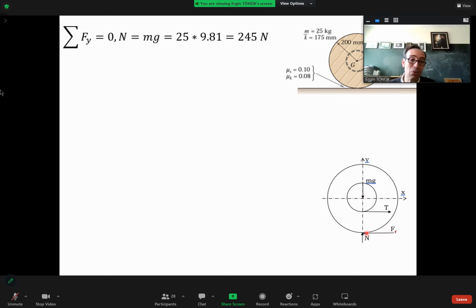The other one would be to the right, that would try to resist the angular acceleration. And total friction force would be the sum of these two components. That would be a little trickier, okay? And depending on what the distance is, how it's going to move, one of those might be larger than the other, so the total friction force would be the sum. But here we are lucky, both create the same direction. Okay?